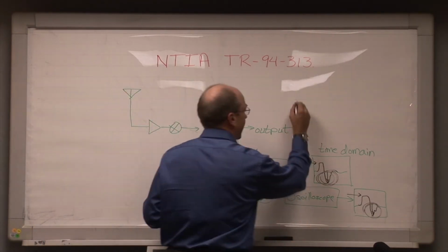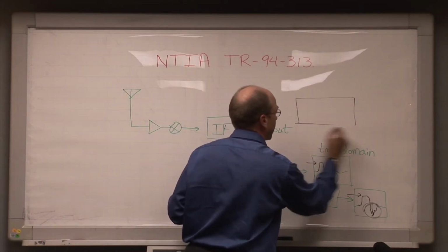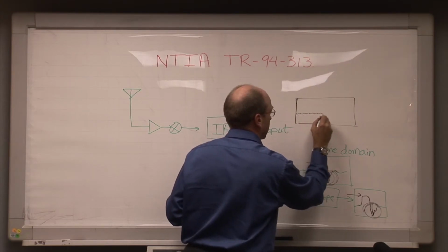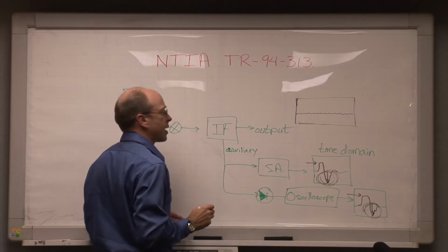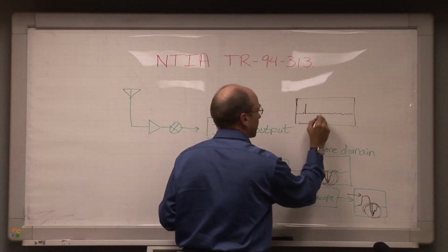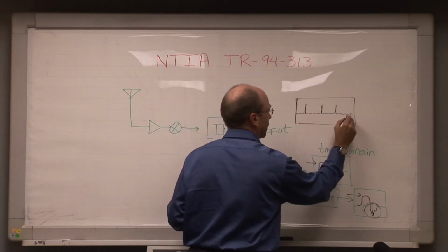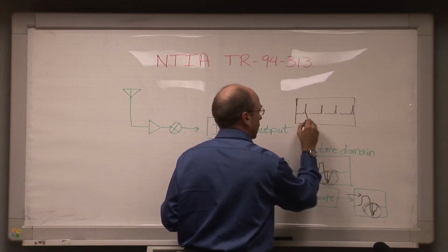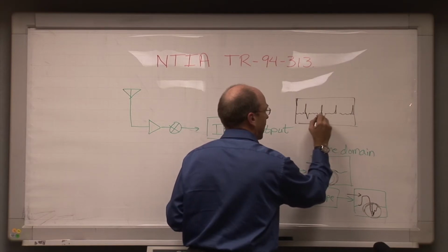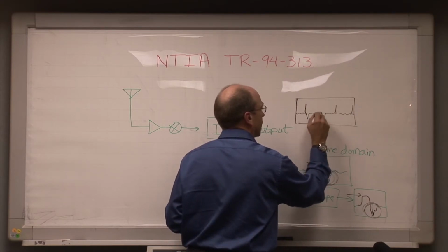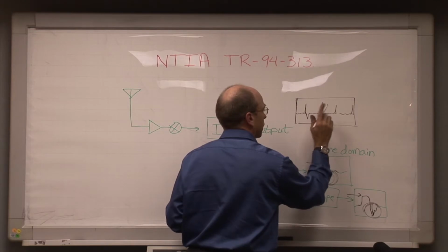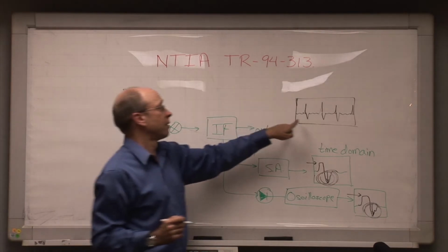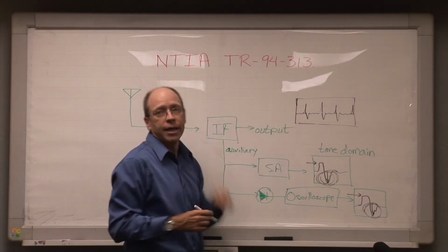And what you may in fact see on a display if you go to a longer time base is first of all the characteristic of the receiver and the IF, and then if it's a short time base, you'll see a set of pulses, for example, coming in from whatever the source is, and then you'll see this happening right after. There we go. See this happening after each one. That's it. That is our front-end overload. That amplifier is losing its gain characteristic at that point.